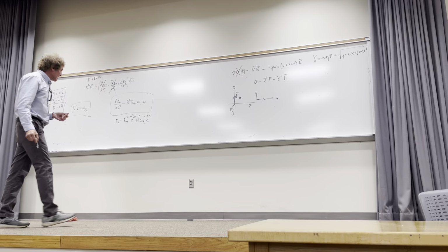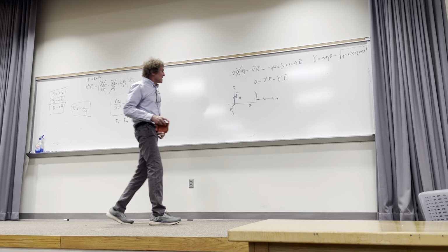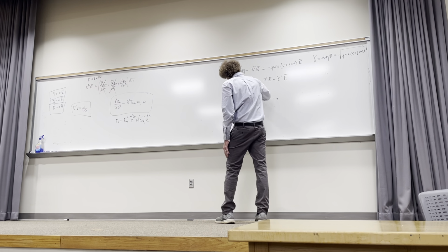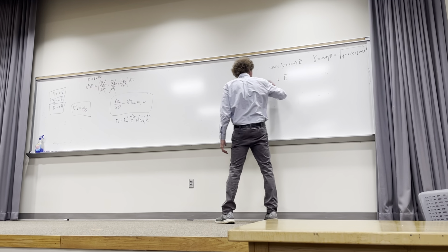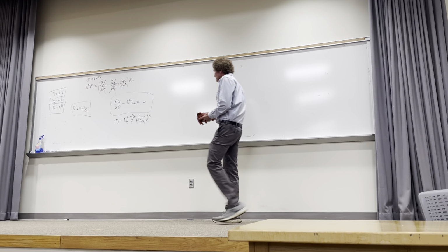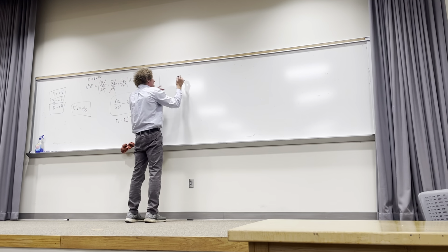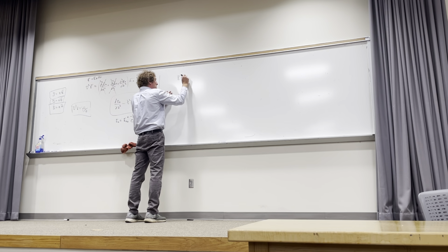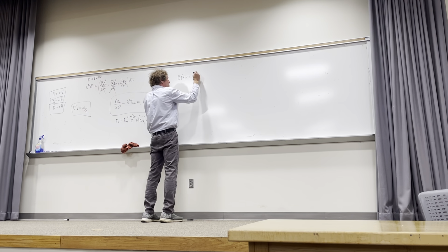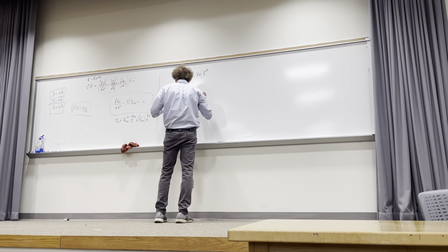It's going to be like this. Now, when you have this, come over here, and what actually happens is this. If I wanted the time domain form, if I wanted the E field in the time domain, as a function of z and t, then I would take the real part of e to the j omega t times this.